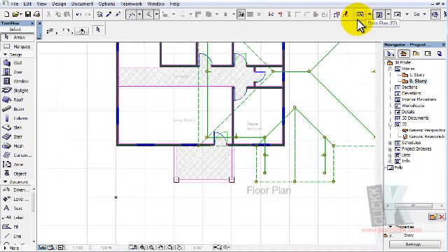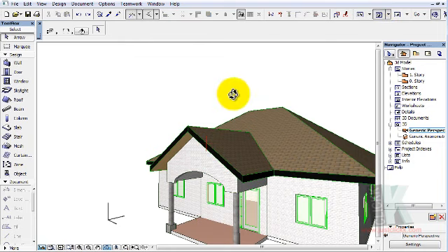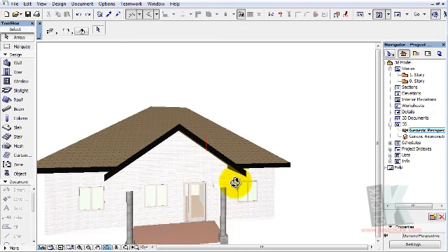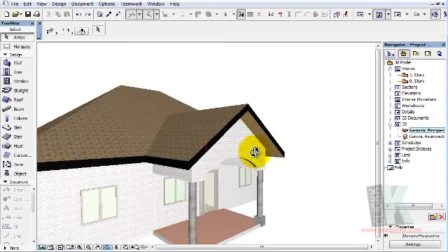Wow, that's it. Let's undo and get everything back in place. Alright, it's in place now, but still grouped. Alright, everything is grouped. So that's how you ungroup and modify your roofs. Every component in ArchiCAD, you can ungroup, modify, and regroup back, because that is how it works.